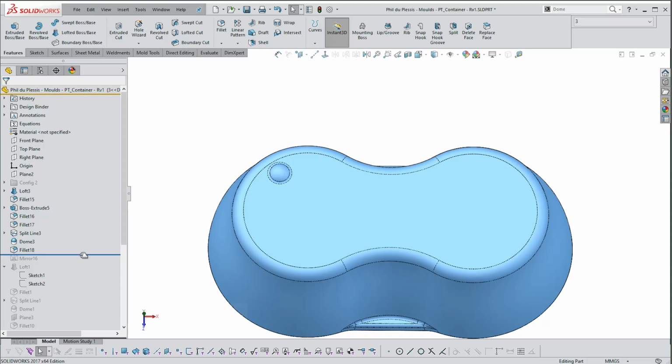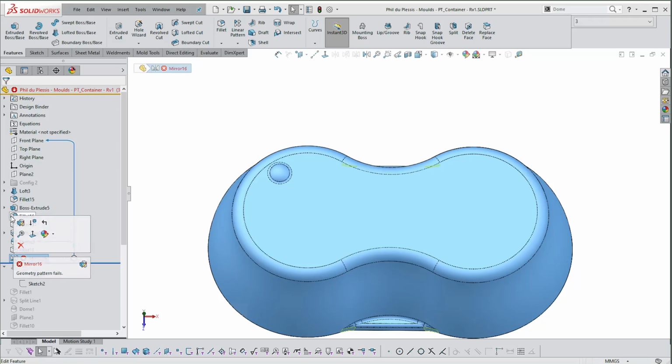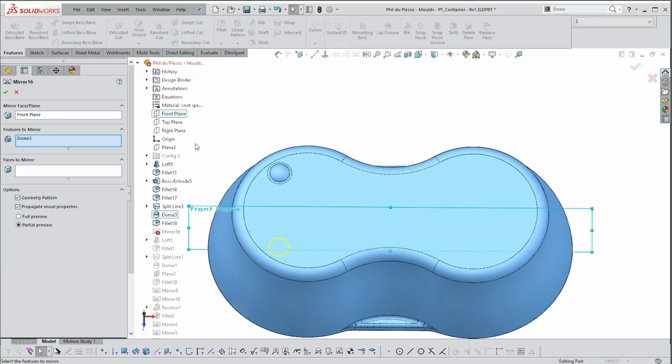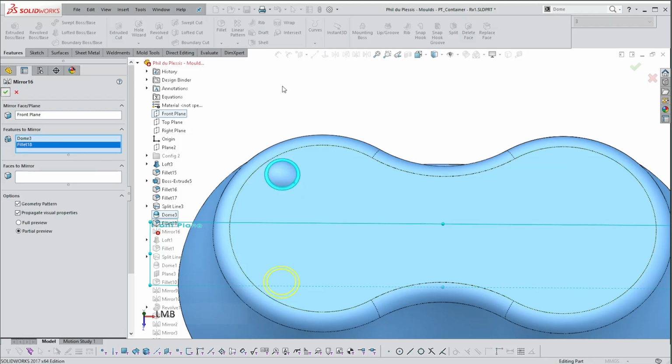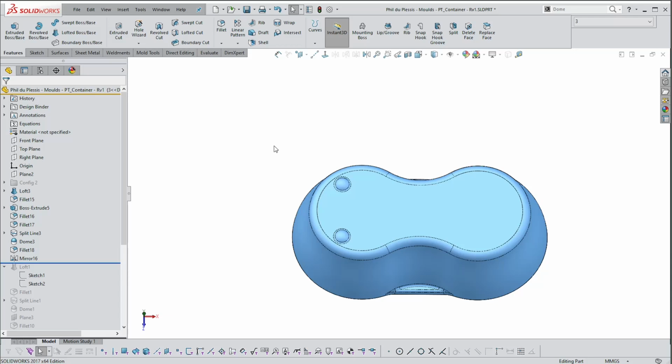And then when I drag this back down, I might get an error message. I do. So all that's doing is it's saying, well, you've updated, but you haven't told me which features you want in this mirror. So go back to the features mirror command bar and just select that item there. And there we go. Okay, and then we're going to mirror those across the other way.